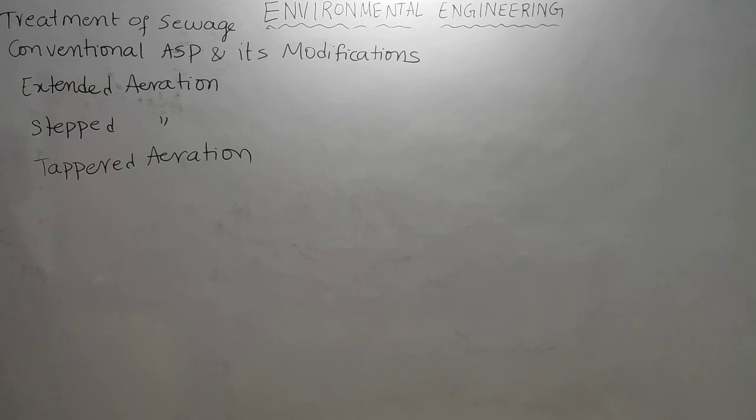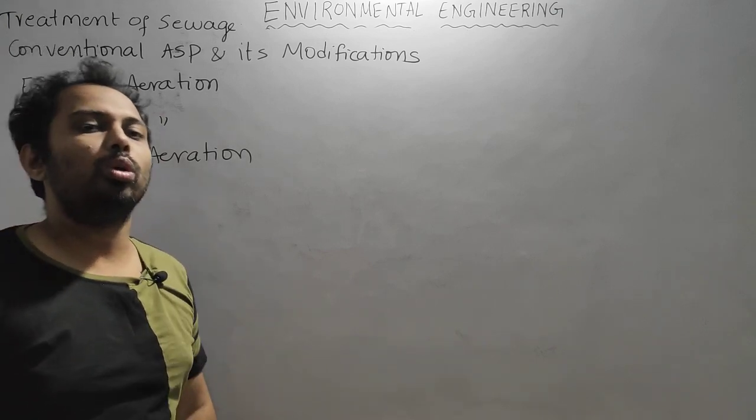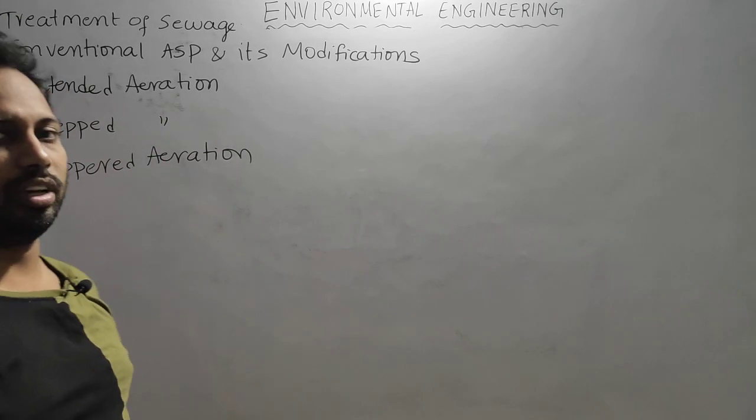Generally it takes a lot of time and is also uneconomical. But when we are not having any primary sedimentation tank, you are directly doing activated sludge process treatment only. In those cases, we generally prefer this kind of extended aeration.